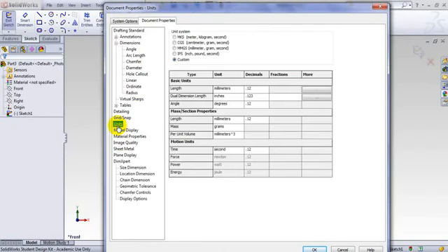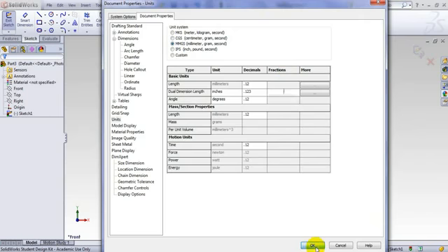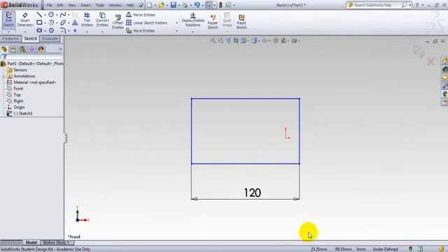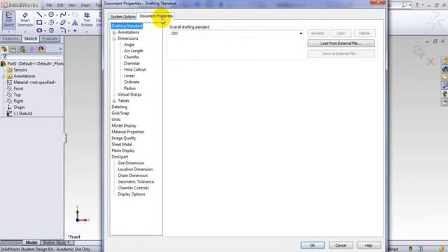The very first thing you should do is define your unit. What unit are you using? Is it SI? Is it foot pound? You can also customize a unit as you wish. I usually use the SI, millimeter, gram, and second unit. Click on here. Now I'm in that unit, so we can go back again here.